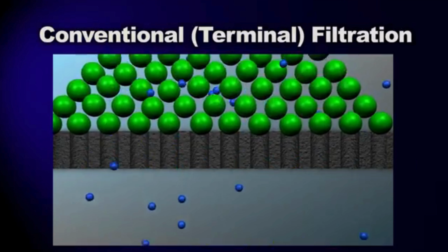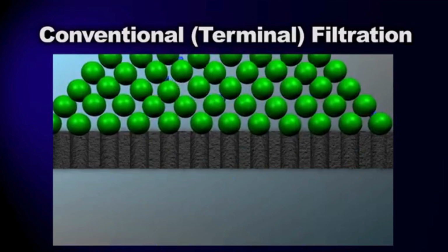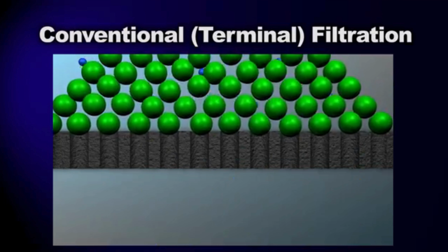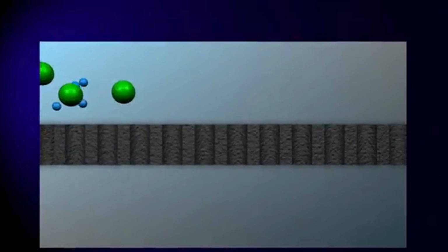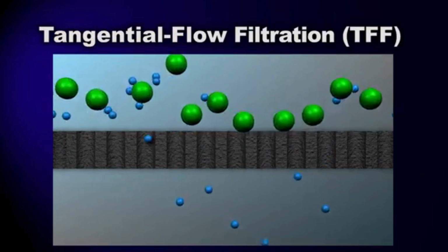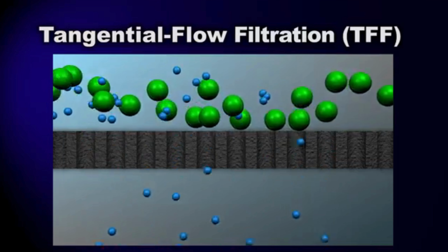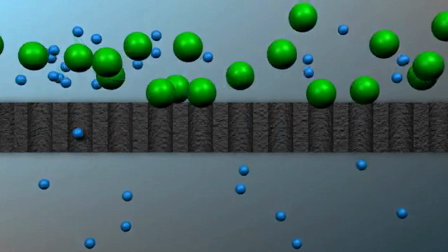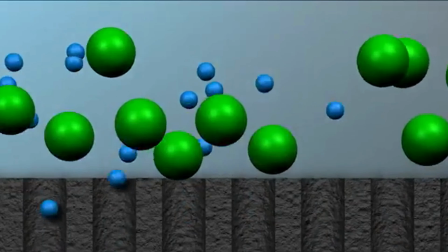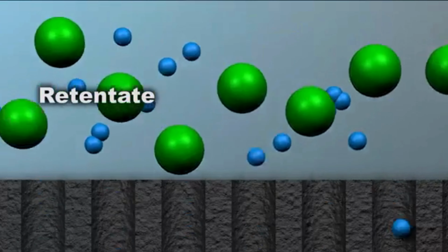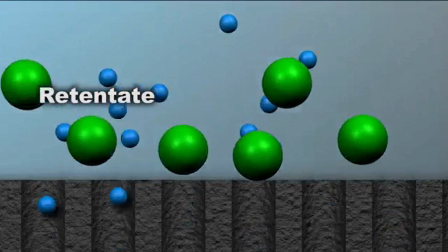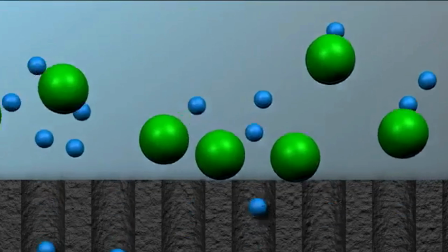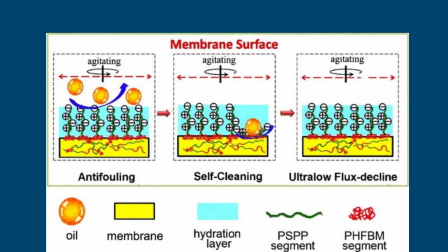Nevertheless, membrane fouling remains an important challenge in TFF processes, particularly in high-concentration biological systems. Fouling mechanisms in TFF include pore blocking, adsorption of proteins or macromolecules onto the membrane surface, gel layer formation, and concentration polarization. Concentration polarization occurs when retained solutes accumulate near the membrane interface faster than they can diffuse back into the bulk solution. This localized enrichment creates additional osmotic resistance that lowers permeate flux and may ultimately contribute to irreversible